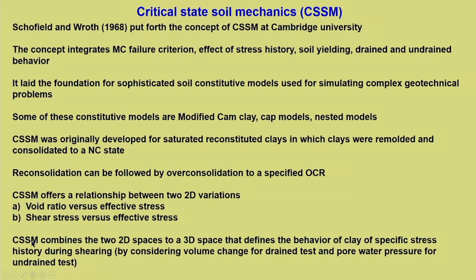So, critical state soil mechanics combines these two 2D spaces into a single 3D space that defines the behavior of clay of a specific stress history during shearing. There will be a particular stress history attached to that particular soil. So, the critical state framework helps to understand the soil behavior during shearing in a 3-dimensional space, which is obtained by integrating the two 2D variations.